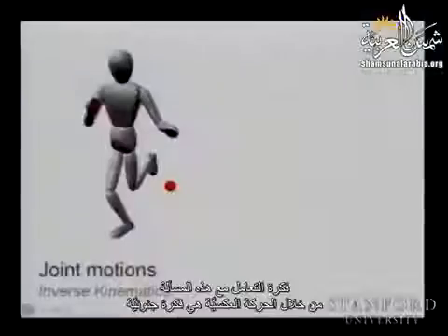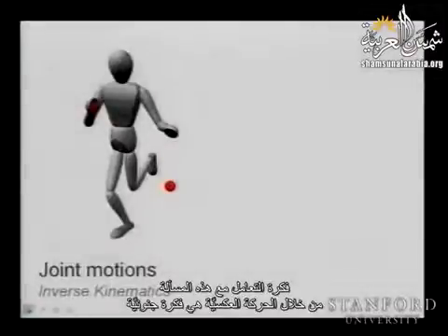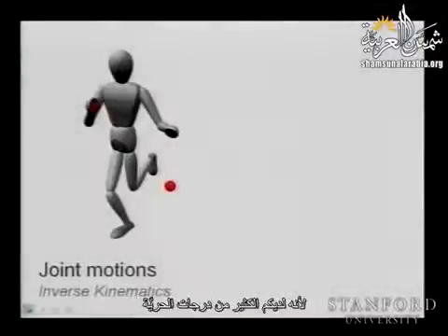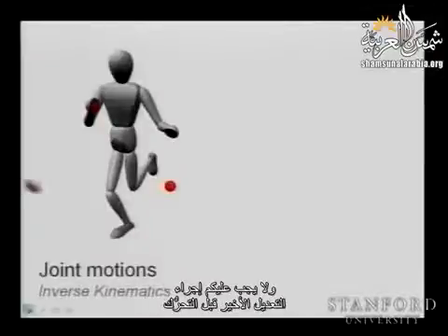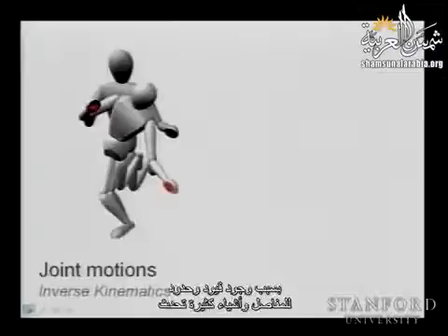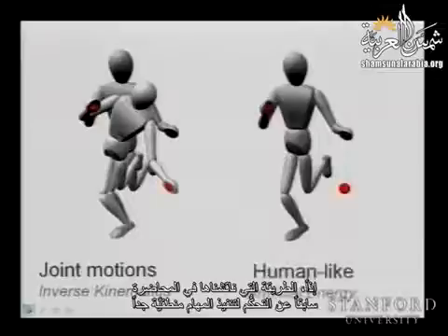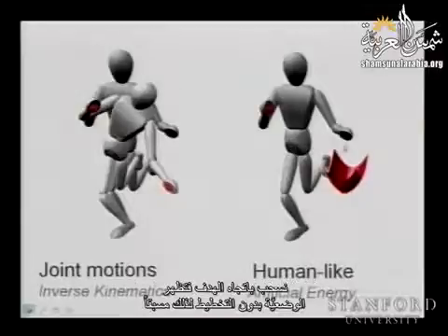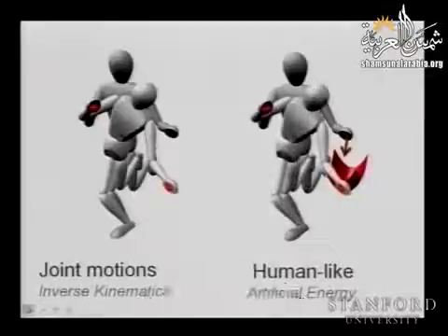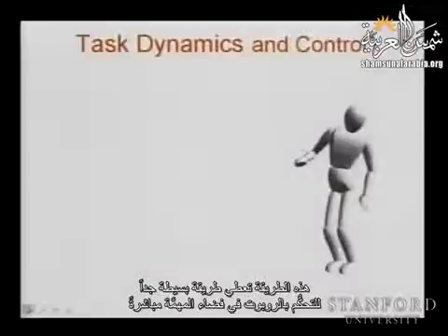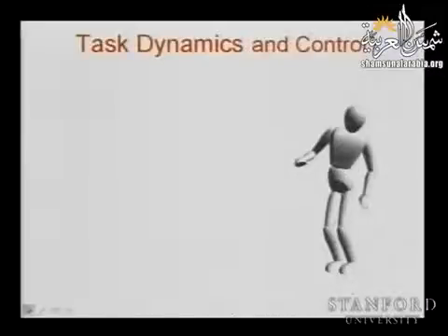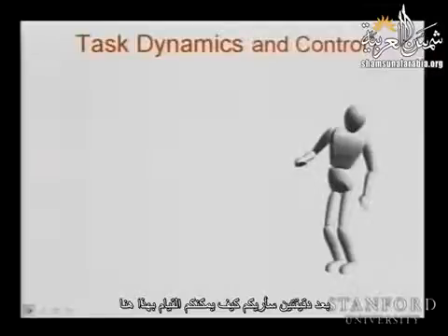So the idea now of dealing with this problem through inverse kinematics is crazy, because you have a lot of degrees of freedom. You do not want to commit to your final configuration before moving, because there are constraints and joint limits and many things that happen. So the approach that we discussed in class earlier about task-oriented control makes a lot of sense. You pull toward the goal and the configuration emerges. You do not decide it ahead of time. And this approach results in a very simple way of controlling the robot directly in the task space. So in the next 2 minutes, I'll show you how we do this here.